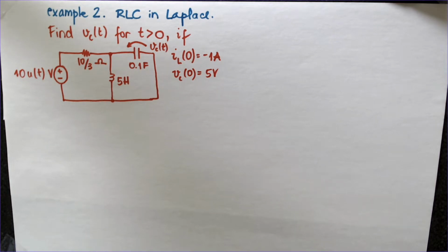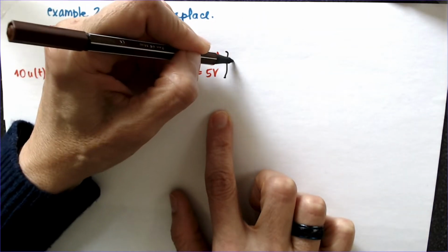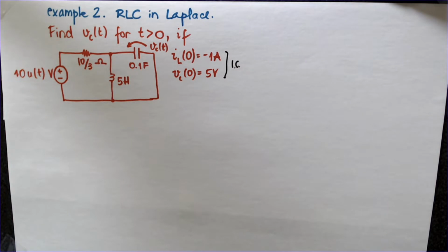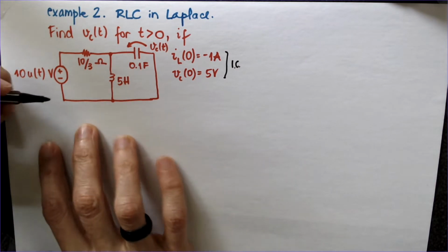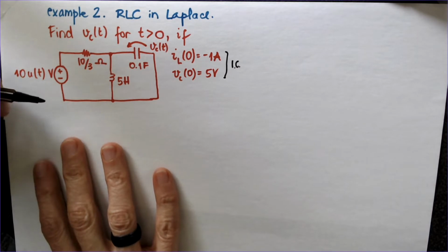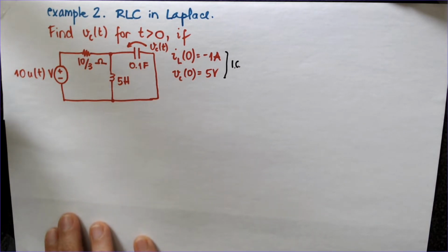So this is the last video that I made an audio for in a different file. This is an RLC in Laplace, and we're going to start with the initial conditions here. That would have been the first step. Usually it's going to take much longer to solve a circuit like this. We're already going to go to the second step, which is to draw the same circuit in the S domain.